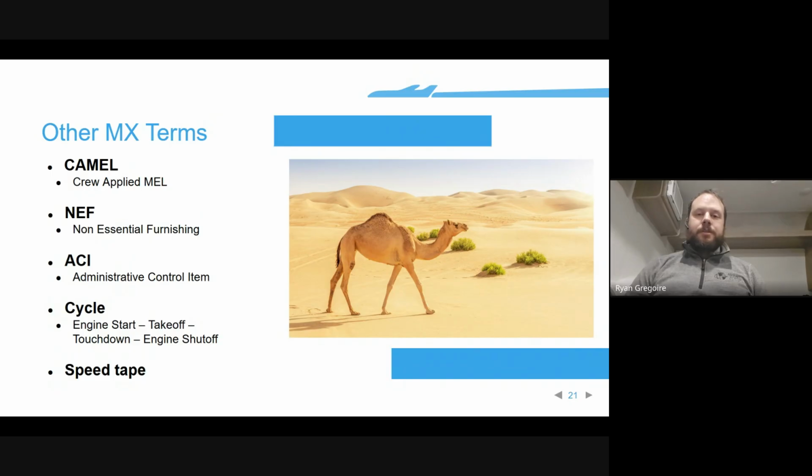And when you see those YouTube videos like, oh my gosh, they've duct taped the wing on, no, that's not duct tape. That is speed tape. That is there to provide aerodynamic efficiency, because there is something wrong, or it's covering a seal that's missing, or it's covering a seal that's curing, and they're like, oh, well, the seal can continue to cure as long as we have it covered with speed tape.